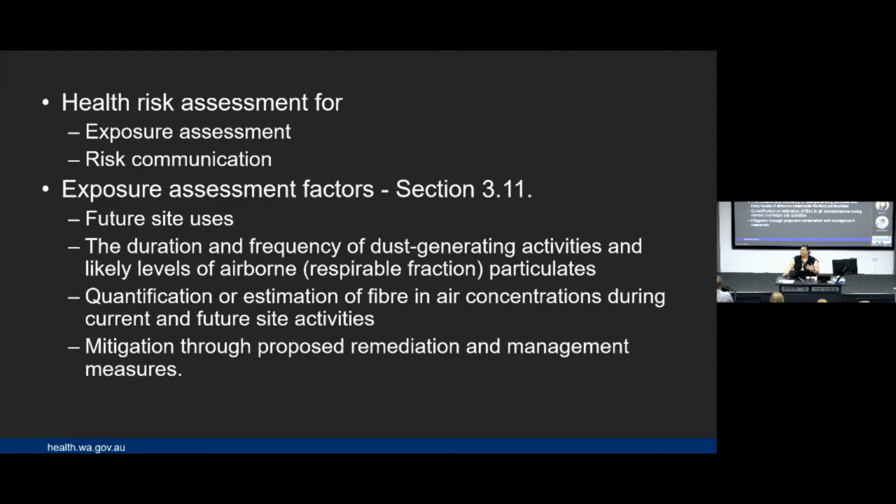But a lot of that, you would now be looking at definitely including air monitoring as part of your assessment stage for health risk assessment. Looking at air monitoring for activities that either have happened or will happen on that site. Now, a note, because we have WorkSafe here still: if you are doing any simulated activities, which we have done at some sites, depending on the level and type of contamination present, you may need to actually get WorkSafe Commissioner approval to disturb the material to do that kind of testing. So just be aware of that. You can do it, but you may also need WorkSafe approval before you start because you are disturbing asbestos.